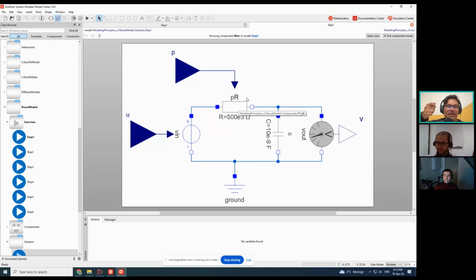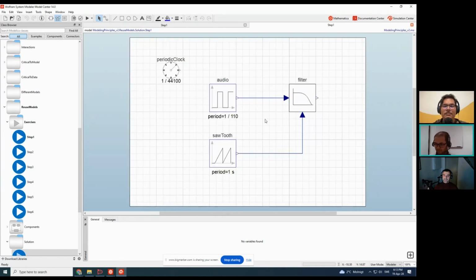We are simulating that we are twisting the knob. And the voltage input is the pulse input that you mentioned, right? We are measuring the voltage of the capacitor, and we will get this filtered signal. This is a digital replica of a real physical system. You're saying it's a simulation of what will be an analog circuit.